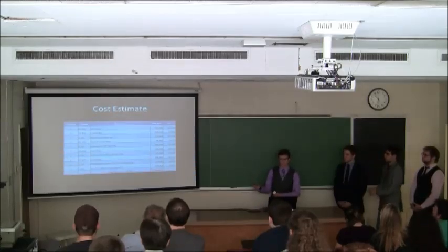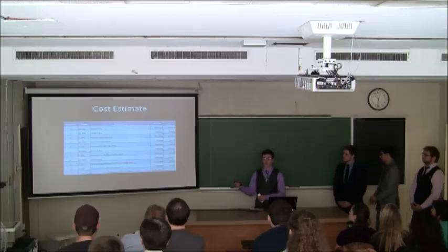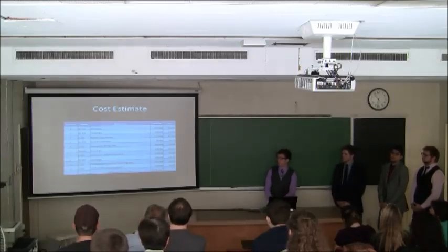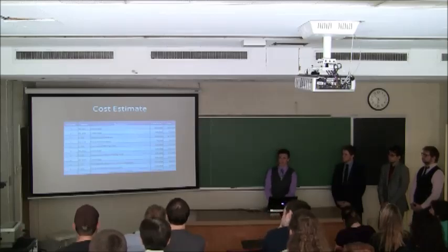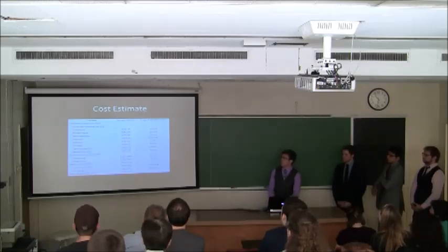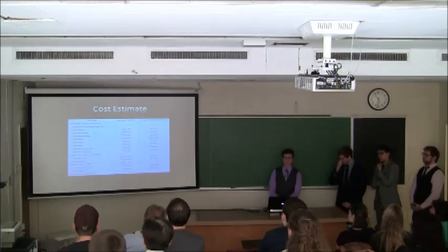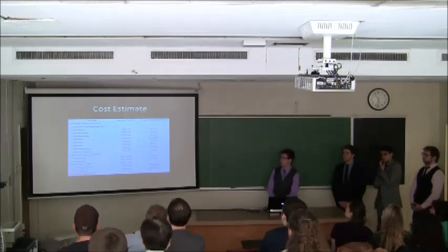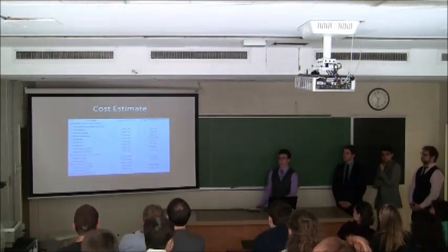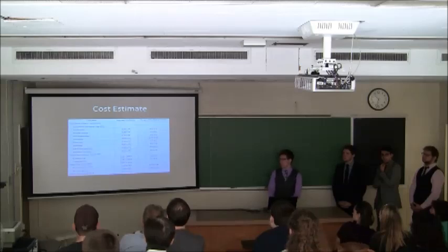Like I said, we use SuperPro Designer, so we obtain these equipment costs from SuperPro Designer, which are based on the average market values for the various equipment that you see here. And we came up with a total purchase cost of $2.5 million. So this was used to calculate how much it would cost to start this facility and the direct fixed capital that we would need. This is done by using multipliers to calculate direct costs such as installation of equipment, process piping, equipment instrumentation, along with indirect costs such as the engineering and construction. And then we added contractors' fees and contingency finances.